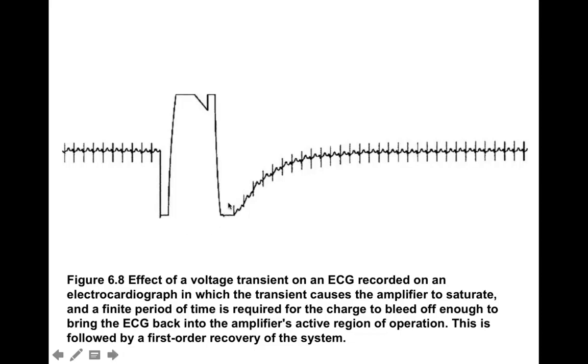So this is what's referred to as the first order kind of recovery of the system, meaning that the system, when in saturation, can be modeled as like an RC circuit that then bleeds voltage off the capacitor and restores the operation of the system.